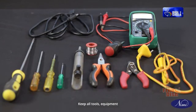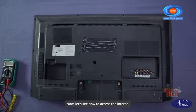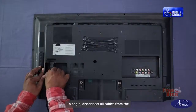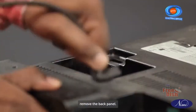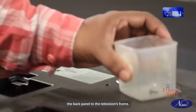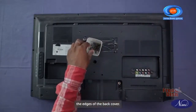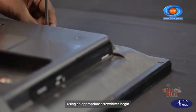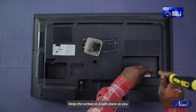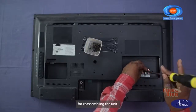Keep all tools, equipment and materials ready. Now, let's see how to access the internal components of the TV. To begin, disconnect all cables from the television and proceed to remove the back panel. Locate the screws or fasteners that secure the back panel to the television's frame. These are usually found along the edges of the back cover. Using an appropriate screwdriver, begin unscrewing these fasteners methodically. Keep the screws in a safe place as you remove them, as they will be necessary for reassembling the unit.